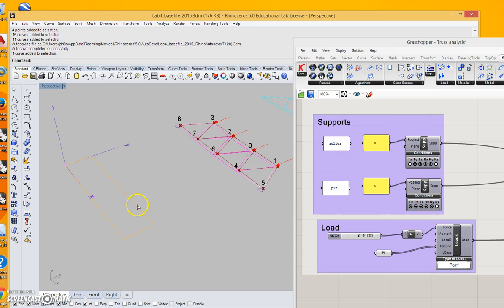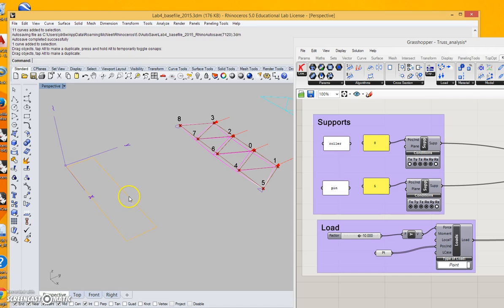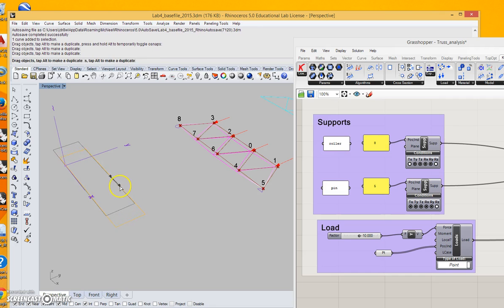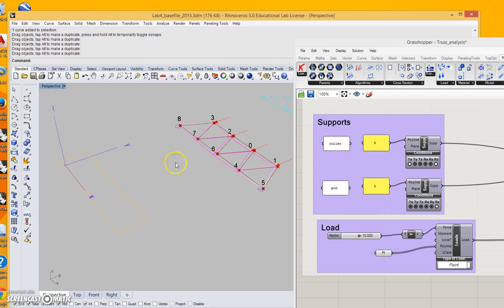So this changes the types of forces that are introduced into the members. So just to visualize that, if this was my beam and I wanted a roller connection, I would want to allow movement back and forth on the x-axis, but not up and down on the y-axis, or not up and down along the z-axis. So this is translation x, y, z. I want to allow translation in the x-axis, not in y or z. When I'm talking about rotation restrictions, that's actually what you're looking at there, is rotation around an axis.